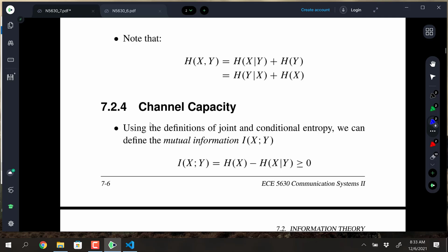Wi-Fi starts off with trying to decide what modulation scheme to use based on the channel and the interference from the other users on the network, the other access points that are around. So it will negotiate the proper modulation scheme because it has to get a certain amount of quality assurance, and it will just reduce the throughput to maintain high quality without too many retransmissions. So it shifts around. I mean, the highest rate is the OFDM scheme, and then the lowest rate would be like BPSK or something like that.